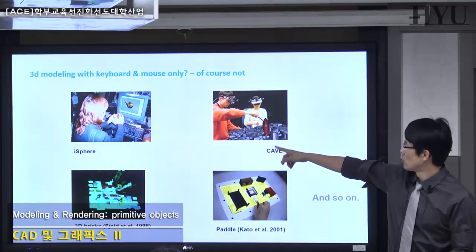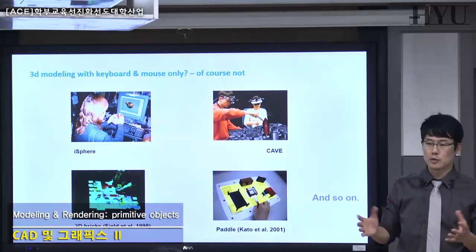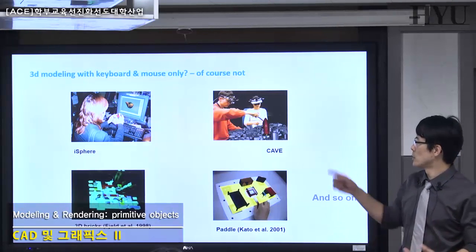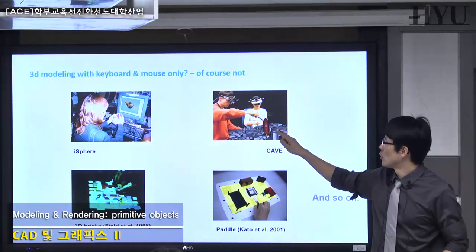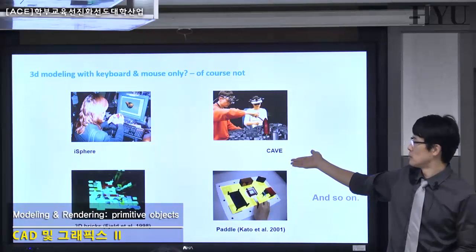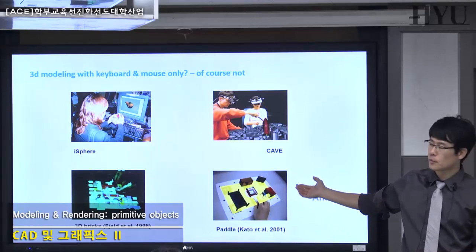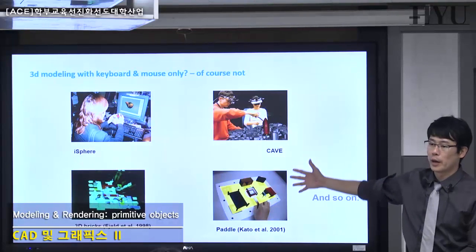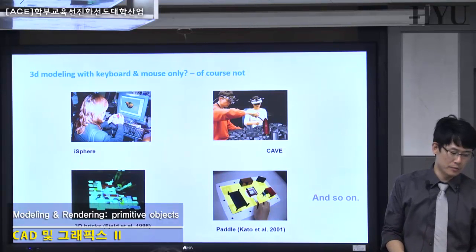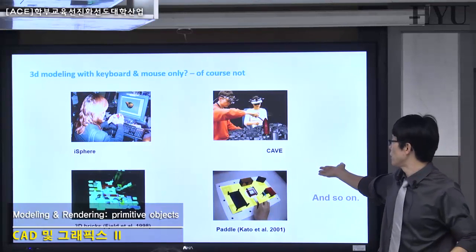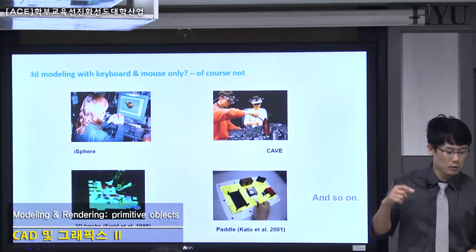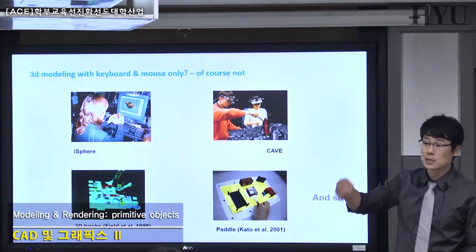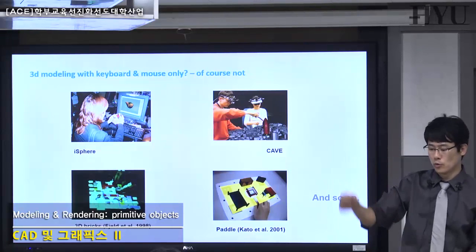In SketchUp, we usually control the polygons using push-pull or edges. But in 3D Max, we can precisely control all the vertices, okay? All the edges, all the polygons, using this one, editable poly. That's one famous and very powerful feature of 3D Max, editable poly, okay? We're gonna learn this one for modifying the geometry.